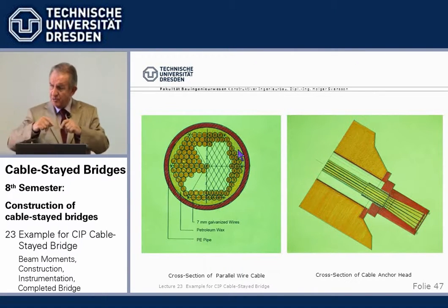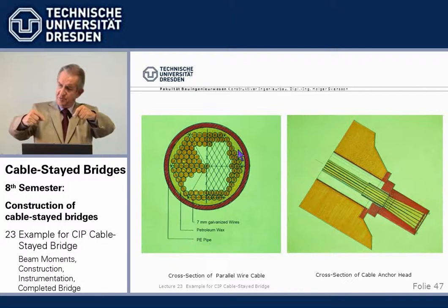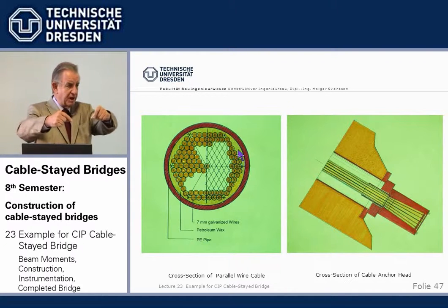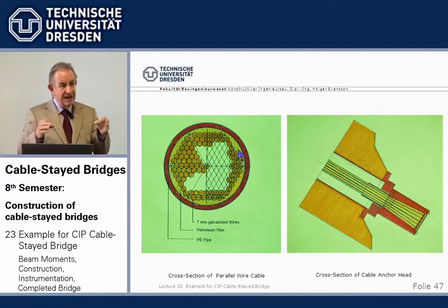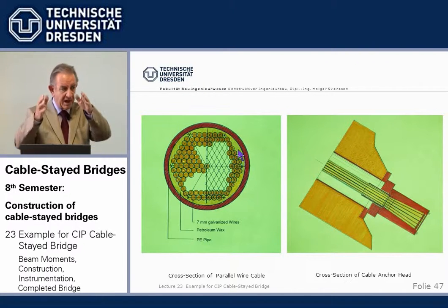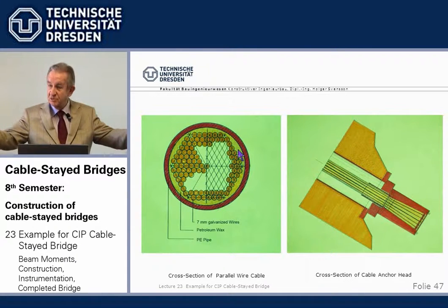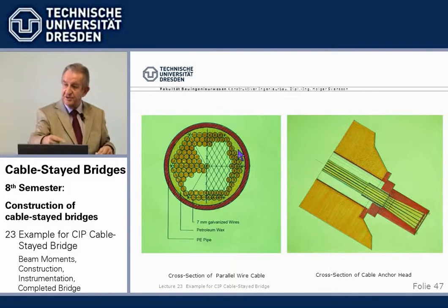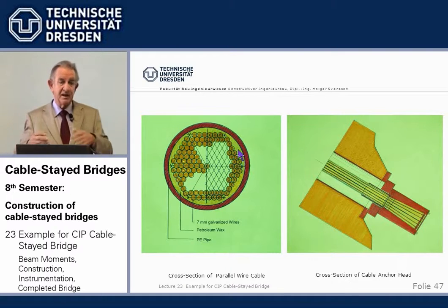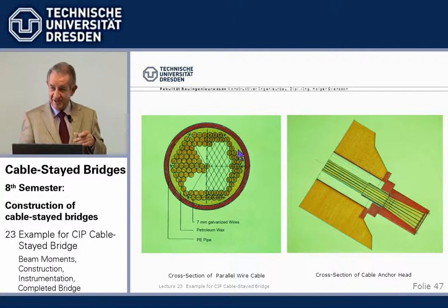But once it's installed and the sun is burning on it and the temperature goes down to 40, 50 degrees, it does not become fluid, because otherwise it would build up a hydrostatic pressure and we could get a big bulb and it could crack. So this is the trick. I like to say it has a consistency of chewing gum, something like that.